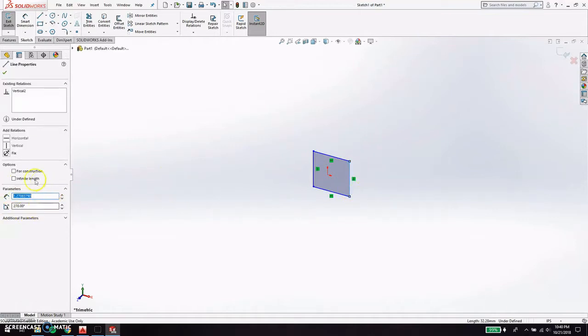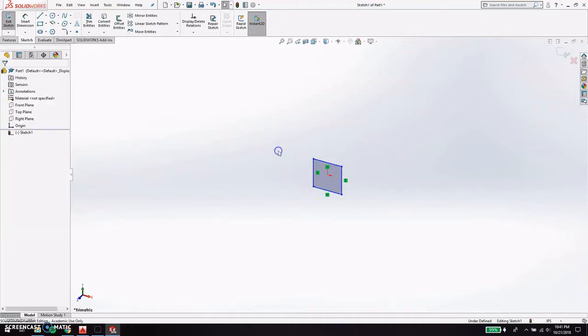So you can see kind of here in the left middle there are these parameters, so you can adjust the length. If I click 1 for each of these, then that should do it. And because they're all oriented with 90-degree angles, I just have to click these two as 1, and then these two should also be 1. So that's it for this. And as soon as you're done, come here in the top right corner. This will load it into your drawing as if you finished your sketch. So we'll click that, and boom, we've got a sketch.